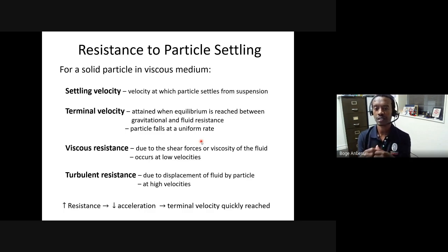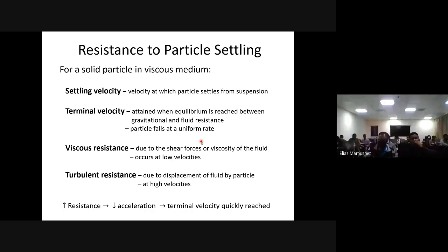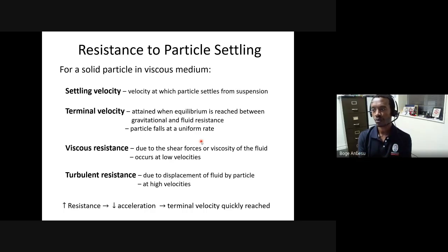Particle-particle interaction can easily affect your separation performance. If particles are not 70% solid, but maybe you're feeding only 10% solid, and the remaining is water, particles are free to move in the separator. So by varying operational factors, you can either make it difficult for the particles to move inside the equipment or make it less difficult. And that depends on a number of factors.